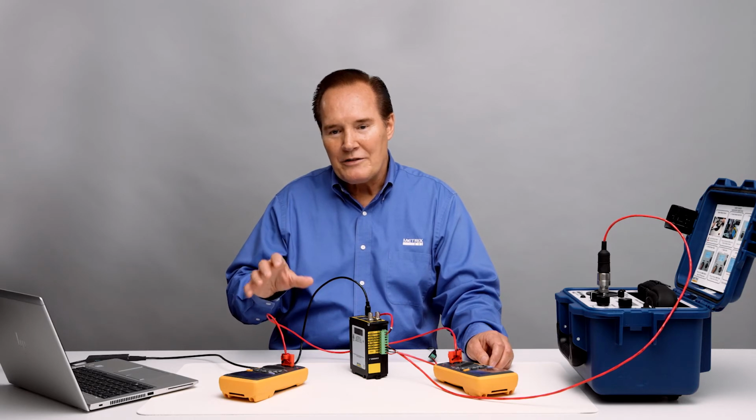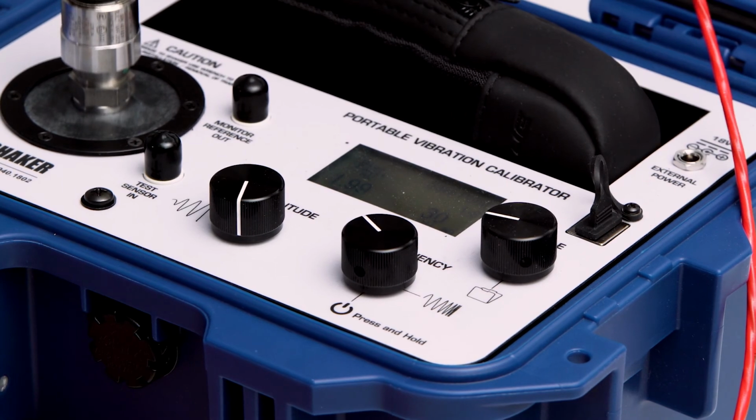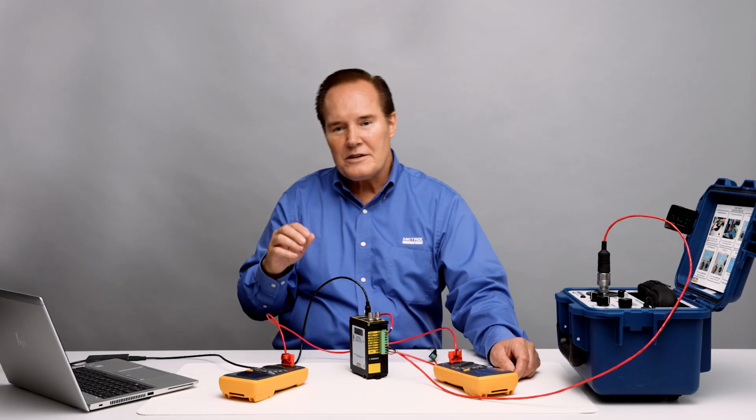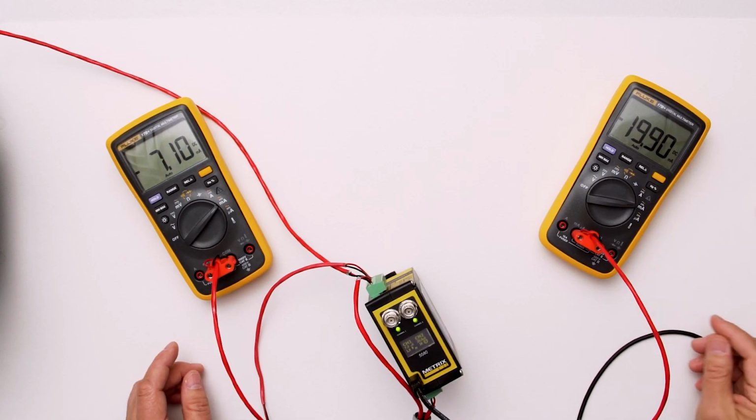So very accurate. But what's interesting is now the impacting events, that's why we read something different, and that's because we changed the frequency. So that's what we're simulating. If I want to take this up to 20, I can do that by taking it up to 40 hertz. 40 impacts within 1 second times 0.4 gives me 16 impacts within the window. So we'll go up to 40. And now we're getting 16 impacts within that 0.4 second window, and we're driving 20 milliamps.